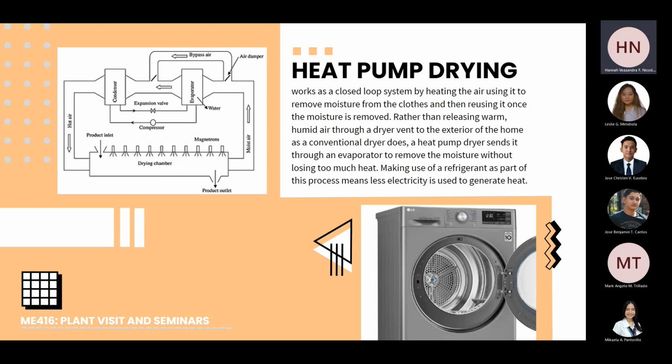The heat pump dryer consists of a conventional drying chamber with an air circulation system and the usual components of an air conditioning refrigeration system. The drying air is dehumidified by the evaporator and reheated by the condenser of the heat pump. The maximum drying temperature is determined by the condensing temperature of the refrigerant used. Heat pump drying is essentially a low temperature process which can be controlled from negative 20 degrees to 70 degrees by selecting an appropriate refrigerant and regulating the compressor capacity and airflows within the system. Next po.